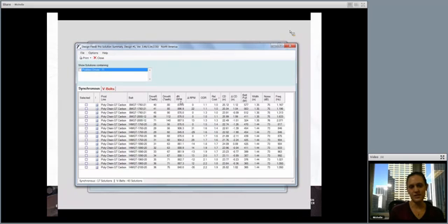You can also sort on diameter. You can sort on RPM. You can sort on over design ratio, or also center distance, belt pull, width, or noise.